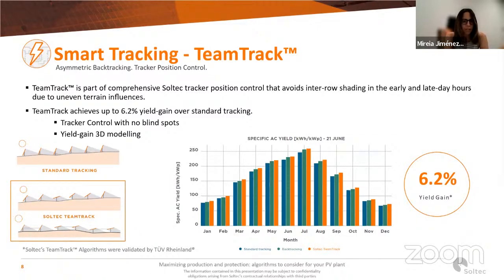Furthermore, the study concludes that compared to the standard tracking, our algorithm obtained between 3.6 and 7.5%, depending on the terrain and climate conditions as well. If a comparison is made to a standard backtracking, annual optimization ranges between 1.2 and 3.5%, more or less. But again, the algorithm gain depends on terrain irregularity and also on the latitude.